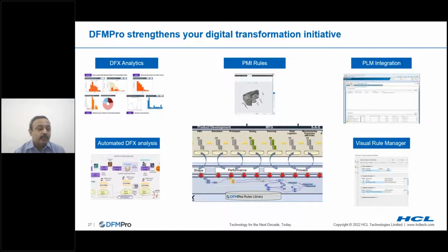So you can have the checks conducted in the design environment by a design engineer. You can submit it to the server for large assembly analysis. You can run it as a batch mode on a large set of parts or assemblies on a dedicated server, or you can use customization APIs to integrate it with certain PLM workflows like check-in based on automatic analysis, check-in checks based on specific triggers, and so on.